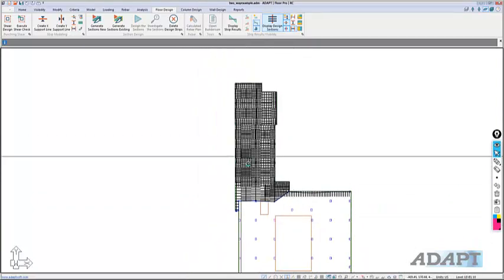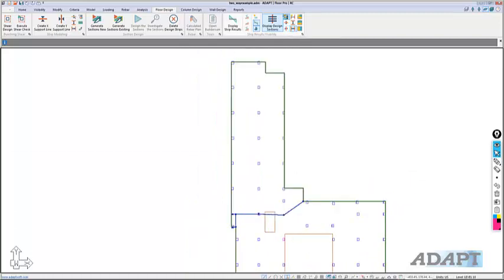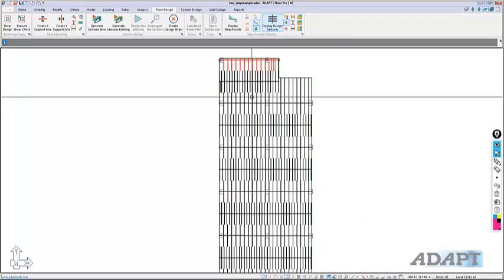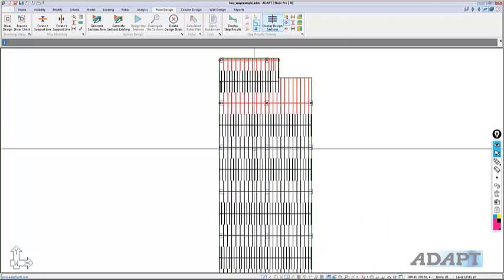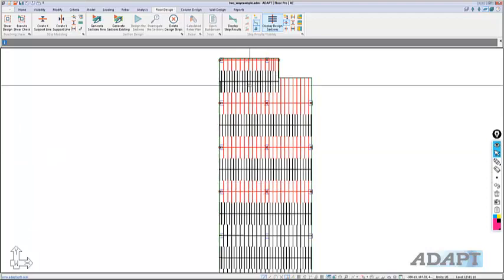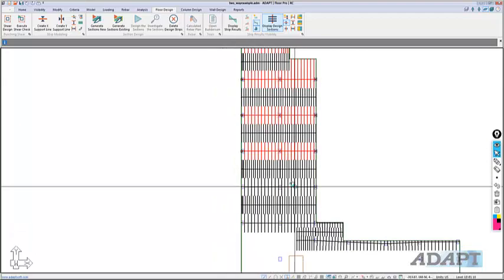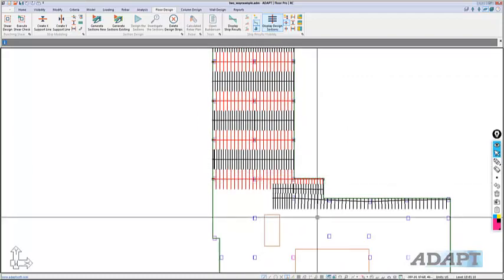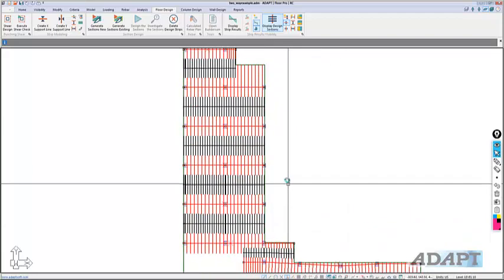Now we're ready to look at these directions independently. So if I go to the X direction, you can see the program. These are my column strips that I'm highlighting. And then the program basically adds in the middle strips where we don't have the generation of the column strips. So column, and then another column strip.